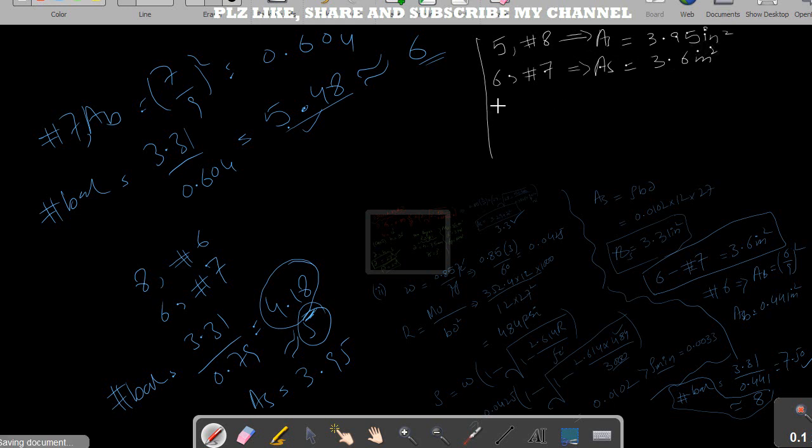And if I use number 6 bar, 8 bars needed of number 6, so this will give me 8 times 0.441, which is 3.52. So I can select more options, right? I can choose number 9 bar, number 10 bar.